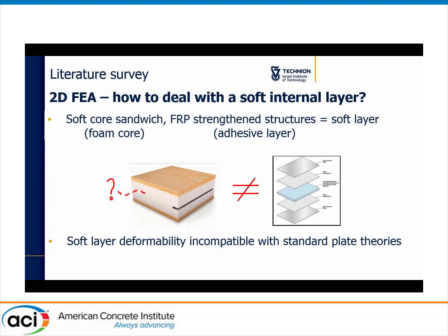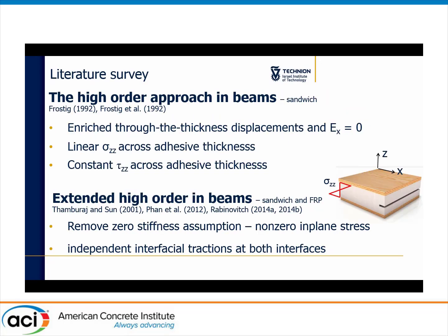The standard plate models used in the stacked plate approach are incompatible with the high deformability of the soft layer, which gives rise to localized stress concentrations and high gradients. In order to deal with the deformability of the soft layer, the high-order approach has been used. The high-order approach assumes an enriched displacement field across the thickness of the soft layer.